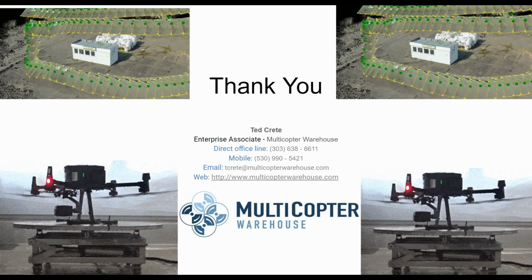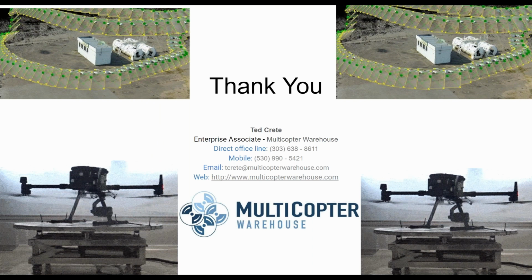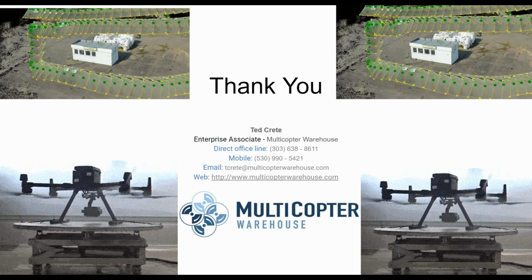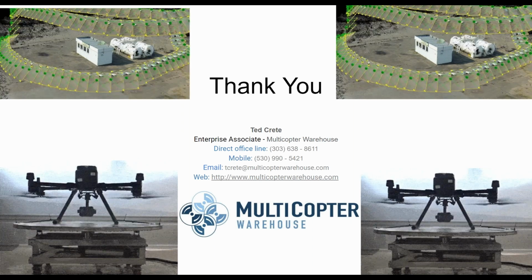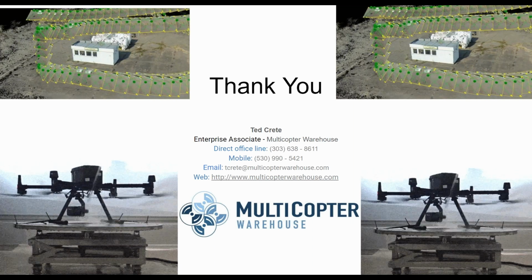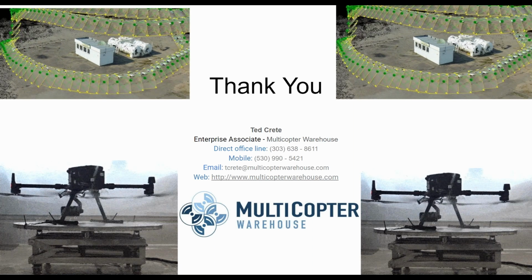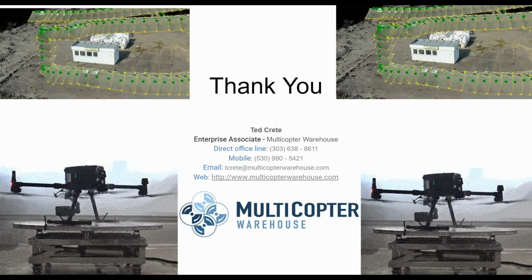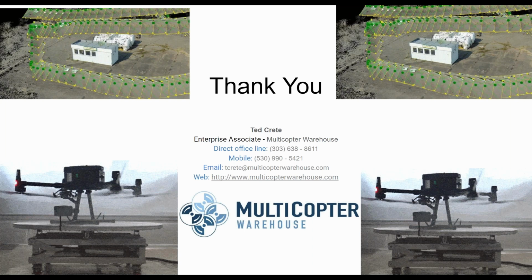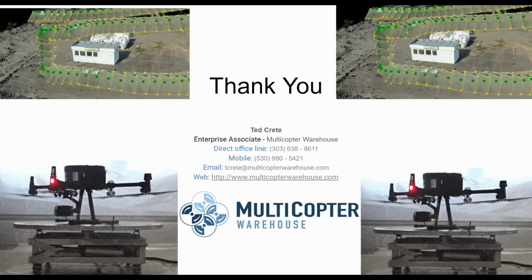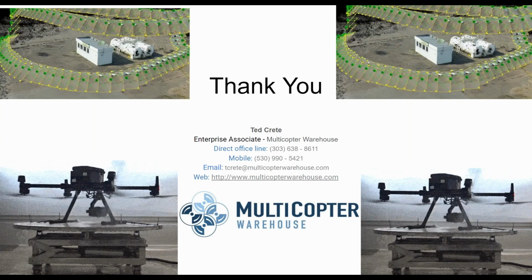So, methods compared to the M600P using only GCPs. What that method is, using only GCPs, is that traditional PPK method that we talked about absolutely first. Like I said, it's been around the longest. If you take your points well with good quality equipment and you are precise in your inputting of the data, it can be incredibly accurate, just like everybody has been using, but it does increase your processing time. It does increase your time spent on site as well.